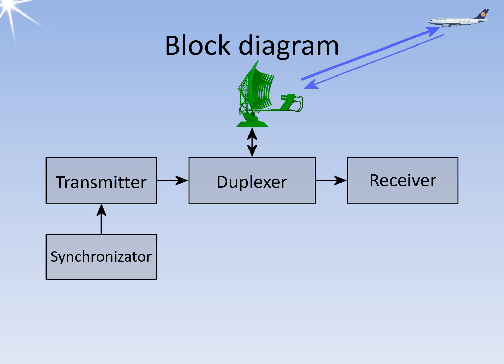A pulse radar operates according to a strict schedule. The transmitter's trigger pulse determines the starting point of the energy transmission and often also the duration of the transmission pulse. The pulse repetition frequency controls the interval between two transmit pulses.